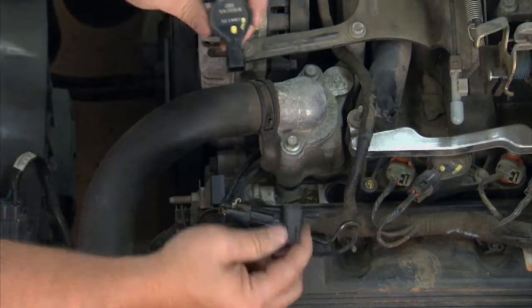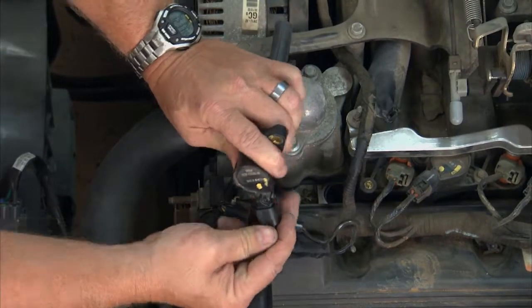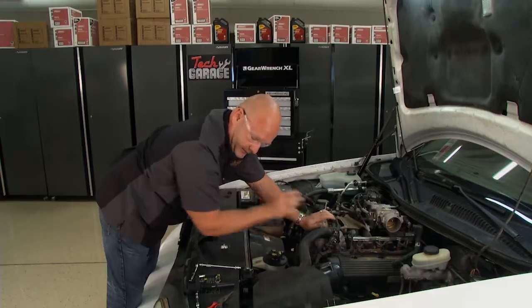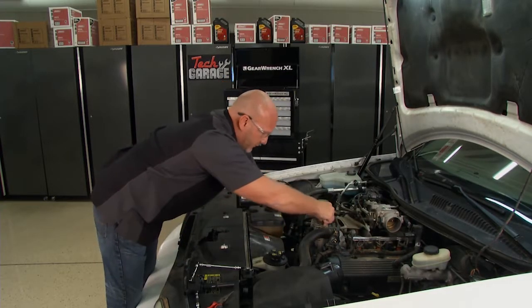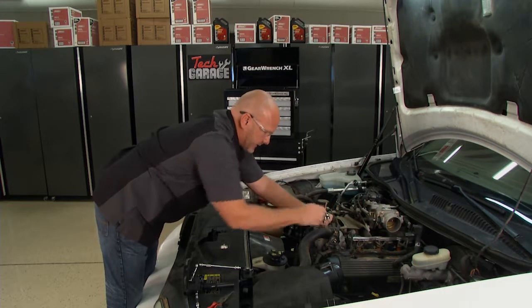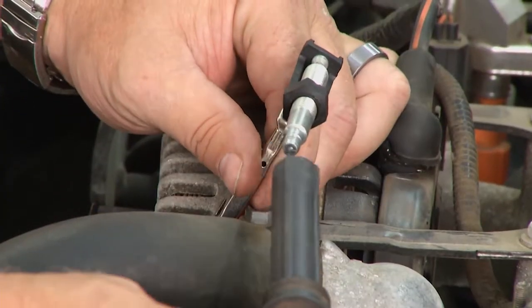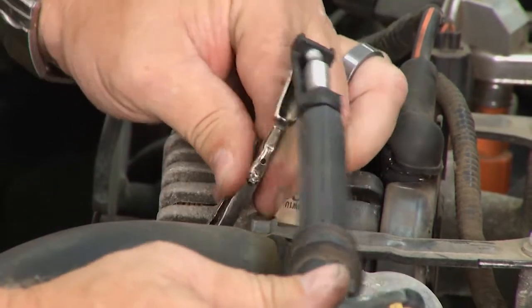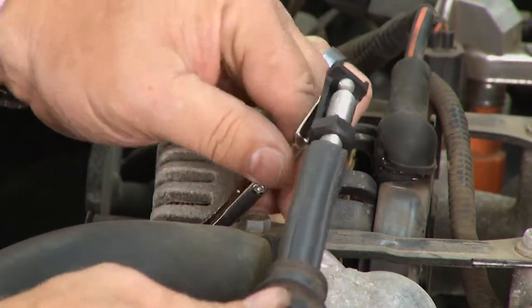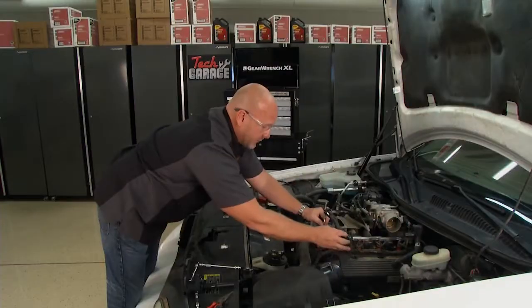I want to reconnect the primary connector so that we're sending an impulse to test this coil. And then a powerful little tool, a spark tester. We're going to create a ground right here. There's a good bracket I can grab hold of. We're going to slide the boot on, and what you should see, if this coil pack was working properly, is spark across this gap. I know that looks like a big gap, but it'll throw the spark there.